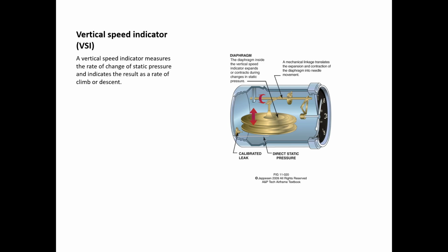Okay, we're going from a pressure factor of 20, all of a sudden we're down to 15. If that happens over a minute, you're going to get a certain calibration. And it looks like they're using bellows or two diaphragms on the inside. There's a calibrated leak. I suppose that's one of the trivia things about the VSI, the calibrated leak.